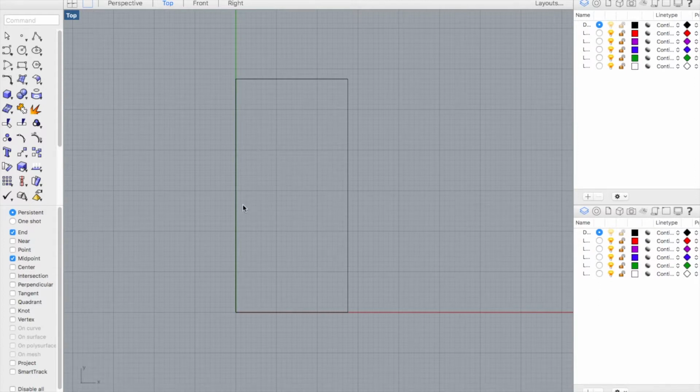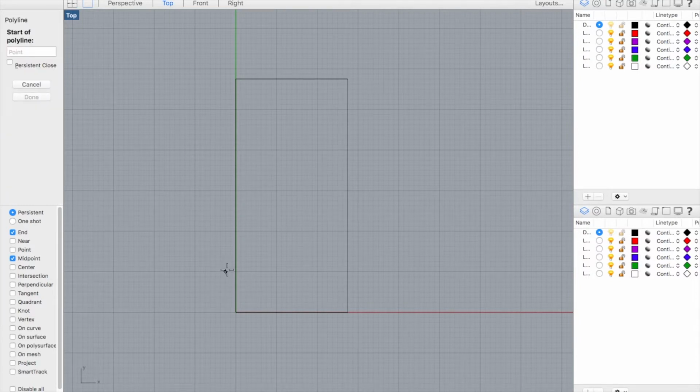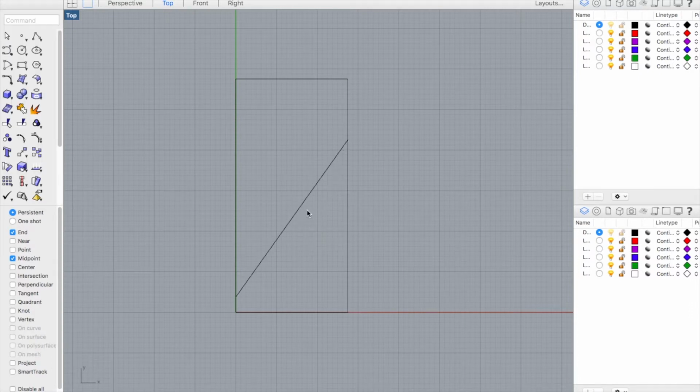If you have a much more complex design, I call it the draw by square or the paint by numbers type of drawing. So you're going to use the grids on your design packet and match them up with the grids here, and you're going to make sure grid snap is on. That way, if you have a line starting the third block up, we can count 1, 2, 3 blocks, click our mouse, and then find wherever it goes on the opposite side, click the mouse again, and there's that line.